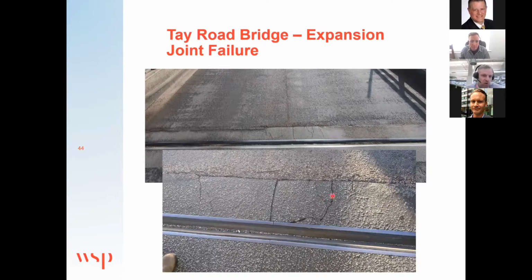Okay, so this is bad. Around this joint, we see cracks. What does that mean? Water's going to get down into that. In the world of radar and water, oh my words, let's think about it. We take a standard radar system. The dielectric of air is 1. The dielectric of water is 81. For road and pavement materials, everything fits around 1, 2, 3, up to about 8, 9, 10. Water is 81, so if you've got water in there, you're going to see a change.